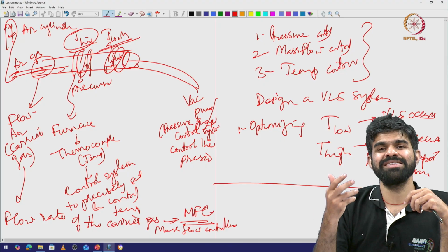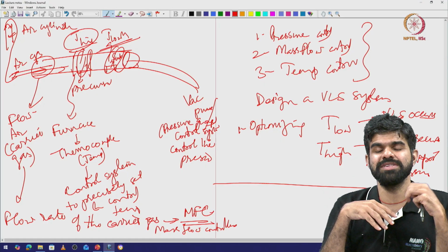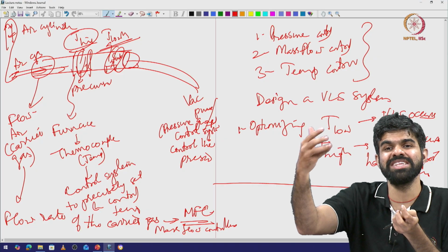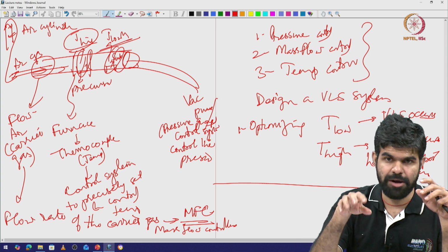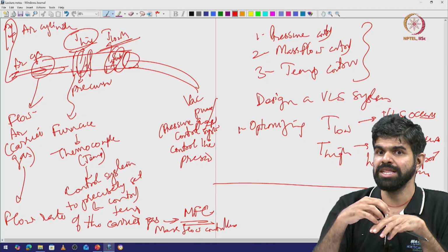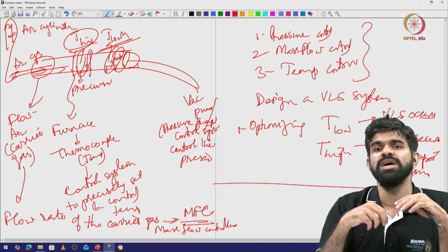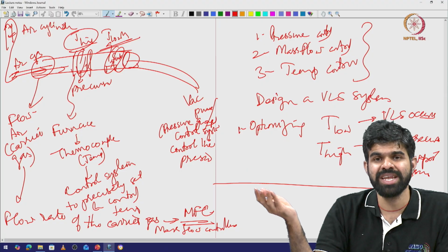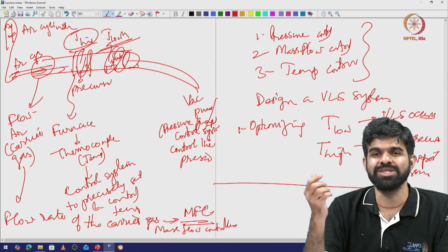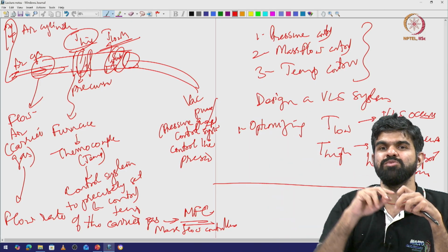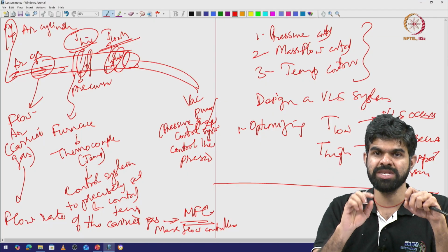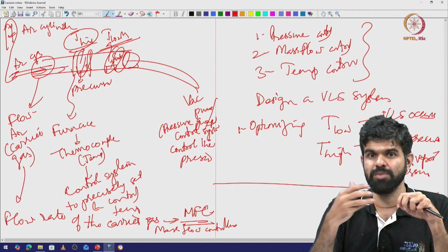But instead of etching, where I am damaging the surfaces and other things, why can't I do it in a nice catalytic chemistry assisted, material science assisted way by using the eutectic phase diagram? That was the idea at that point, right. And then people were able to make these nice silicon nanowires. It's another thing that to scale it to such a large extent, etching based techniques are scalable, whereas VLS turned out to be not as useful and not as scalable in the current CMOS architectures that we use, right. But it is still a very powerful technique to grow nanowires.